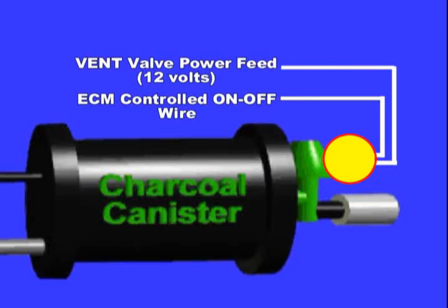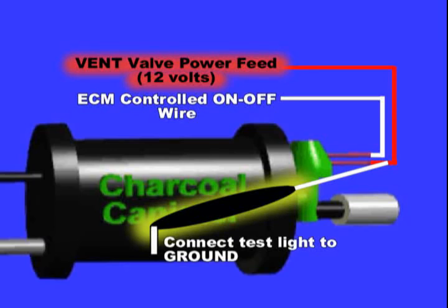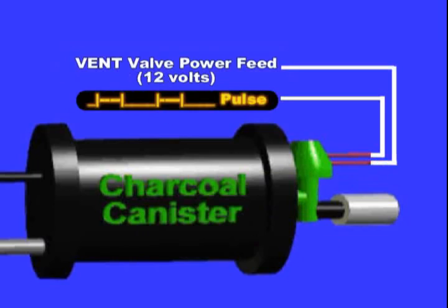To test the vent valve, also connect a small dome light bulb to its connector, start the engine, and look for a steady light. The EVAP system is checked with the engine cool. If no power is seen, using a test light, check for the steady power between battery negative and vent power wire. If no power there, then follow the current to the relay or fuse box. The other side of these solenoids is ground pulsed by the ECM. So, if the ECM is missing a ground, it may affect the EVAP components as well.